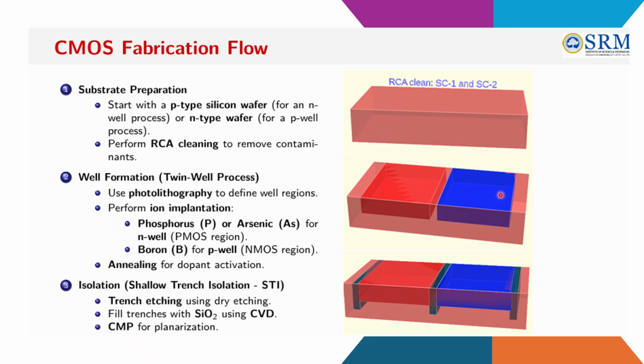Similarly, if you want to design multiple MOSFETs, then you can create multiple wells. Since we are considering the example of an inverter, we need two MOSFETs, an N MOSFET and a P MOSFET. So now these will act as a substrate for our P MOSFET and N MOSFET. Now the question is how will we define the P well and N well? How can we create them?